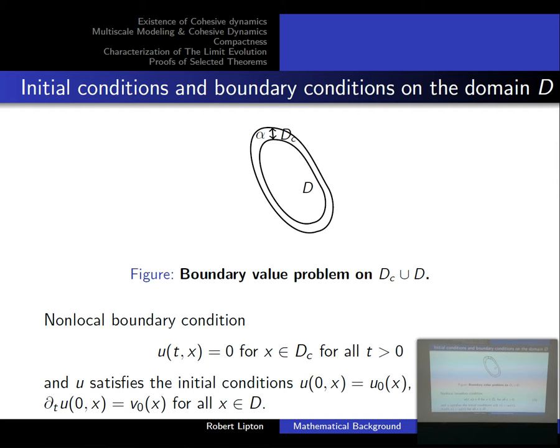Okay, so normally displacement boundary condition is prescribed on the boundary of the actual domain. Here it's prescribed on the rind, and that'll do it for us there. And that way we can have our horizon with the diameter epsilon centered right at the boundary and still be defined. Okay, so our dynamics is still defined for points at the boundary. For points beyond the boundary, so the whole dynamic problem plays out on D, and we have the non-local problem